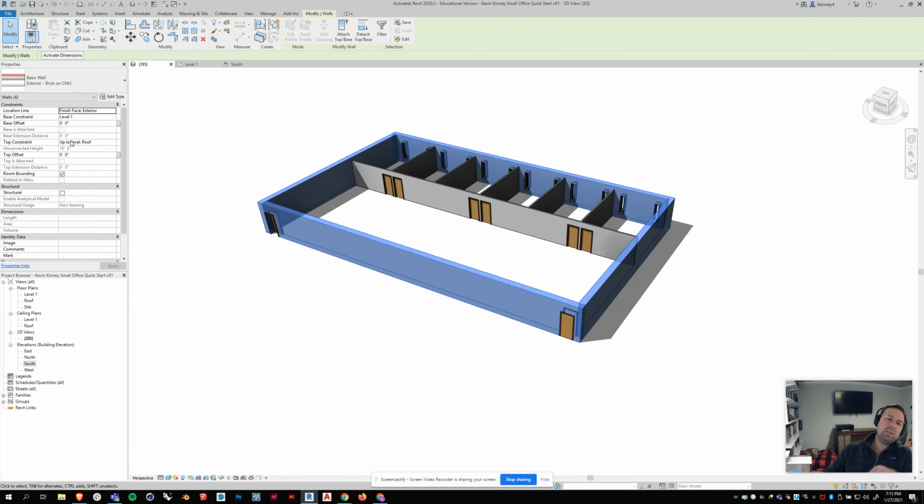Now, what I'd like to do is put a 1 foot thick roof slab. We'll call it a generic material. What is in that 1 foot? I'm not exactly sure yet. And I don't really care yet because I'm just designing. I want that to live right above those interior walls. And I want my exterior wall to go up a little bit. I don't want the roof to be sitting on the exterior walls. I want it to be inset within it.